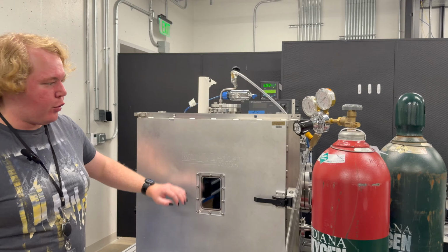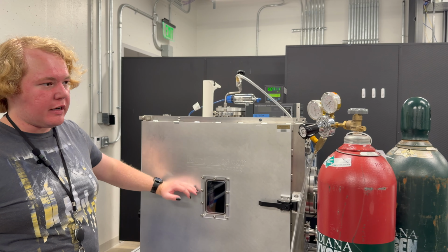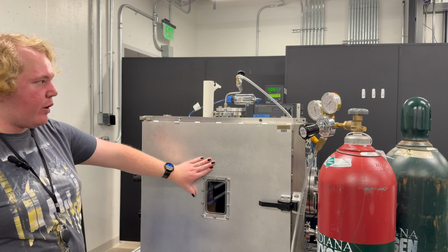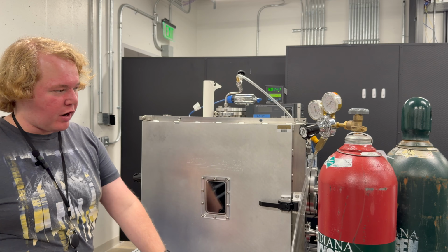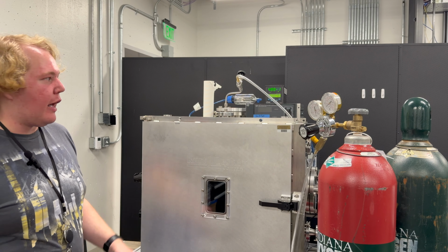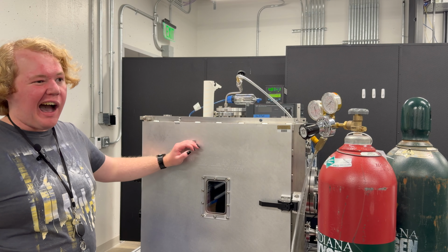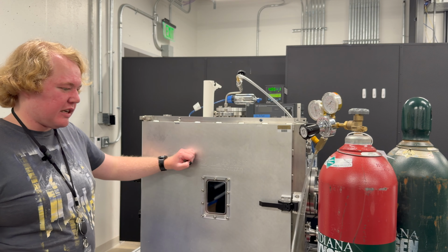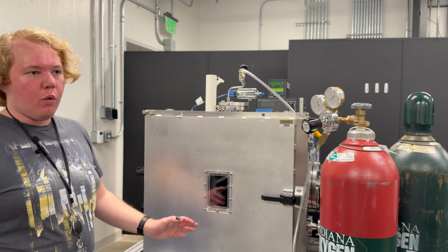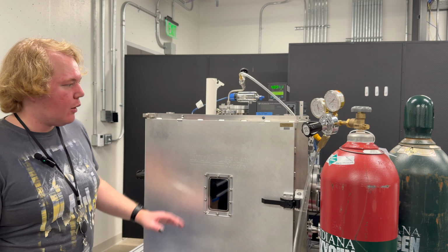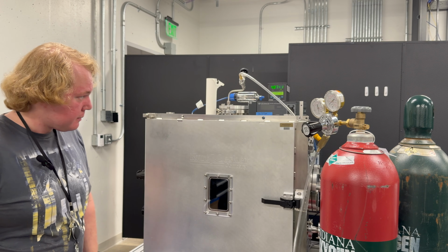And what we'll use that for is to evacuate all of the atmospheric gases that are trapped inside of the microwave absorbing panels, because just using the diffusion pump or the roughing pump is not really suitable, as the pressure differential you can get is not high enough to evacuate all of those contaminants. Because with the diffusion pump, we're able to reach a pressure around 1E-5 torr, which completely evacuates this chamber.